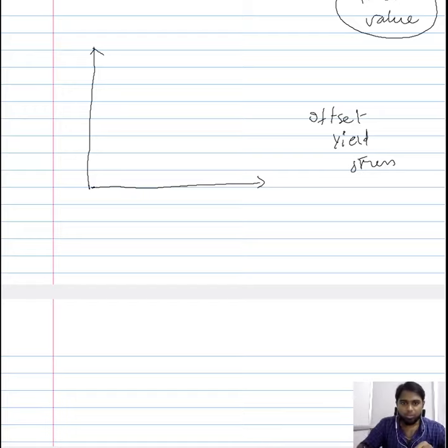Now you have your stress strain curve, you have loaded your material beyond the yield stress, which is of course beyond the elastic or the proportionality limit. So beyond the yield stress, you want to know how much the material has deformed plastically or irreversibly without unloading it.